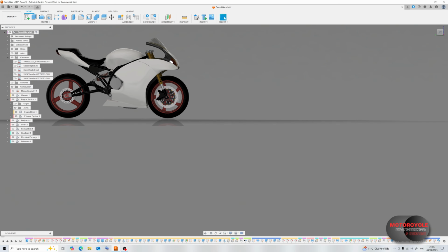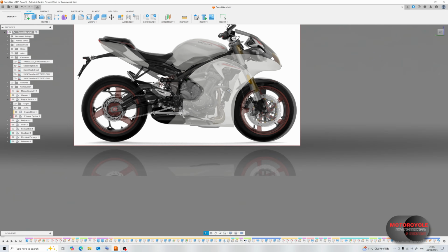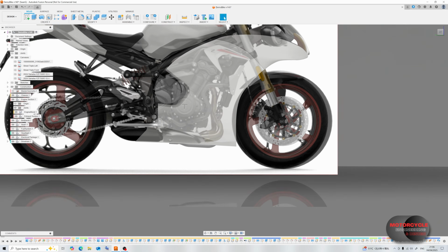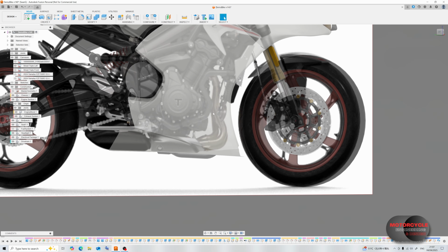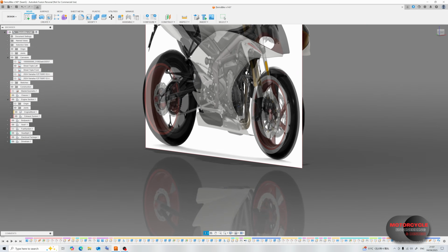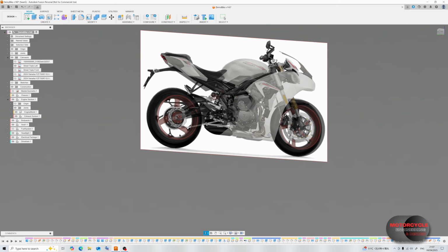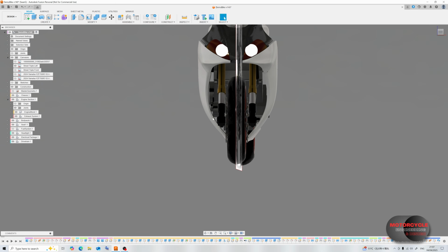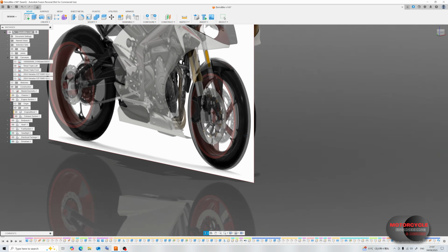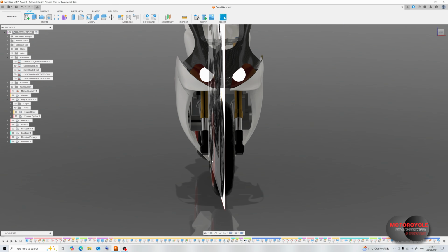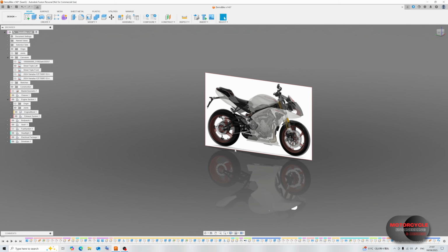First off, it would be useful if before you start, you use some visual reference for your ground clearance. I obviously didn't do that, and I also probably could have used this for reference for sizing the pipe diameter. I have oversized the downpipes on this model. And also another factor is your bodywork. You should probably do your bodywork after you've designed your exhaust system so that you can have enough packaging space, because packaging space is one of the biggest problems for things like exhaust systems.